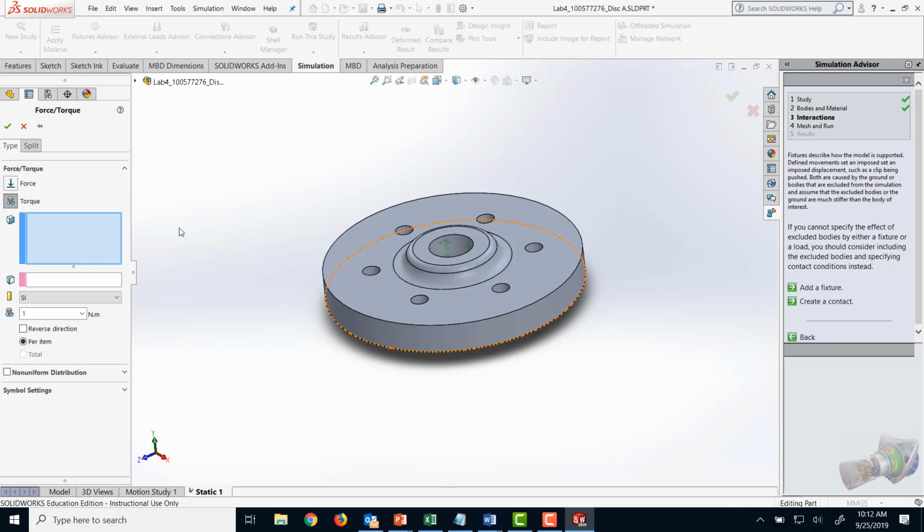So in here, when specifying the torque, I'm gonna select this face. So it's applied at the center associated with this cylindrical face, and for the actual torque itself, I'm gonna pick this face. The direction of this you can change, you can reverse it if you want, but for the purpose of the exercise, it doesn't really matter which direction it goes. If there were other components attached to this part, then the direction would make a difference. To change the direction, all you gotta do is check this box. The value needed for this step is specified as 150 newton meters. And I'm gonna click OK.